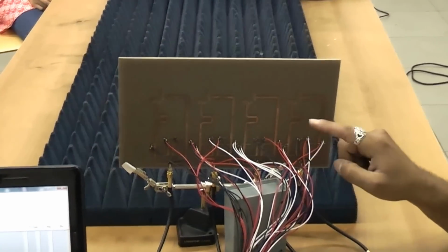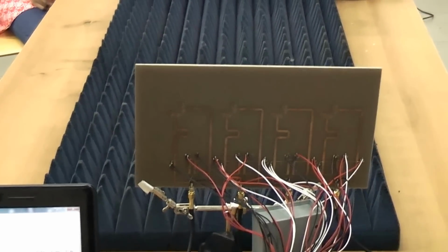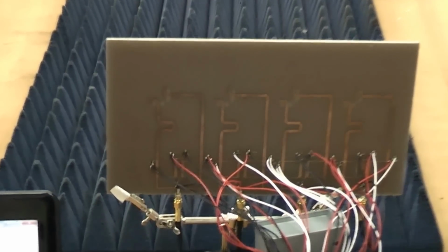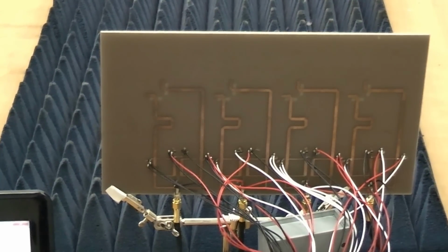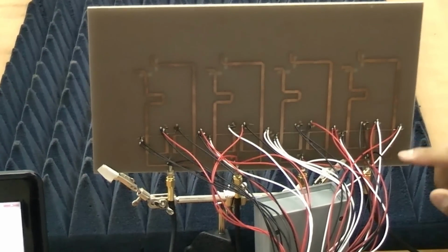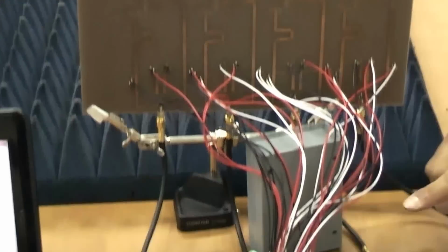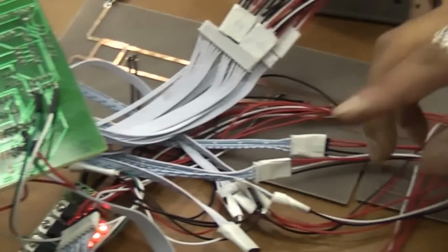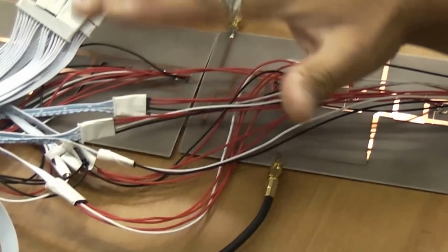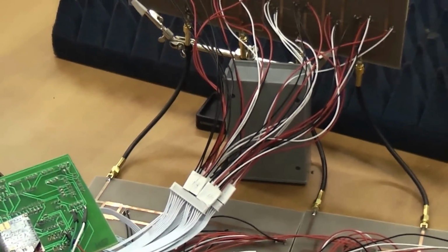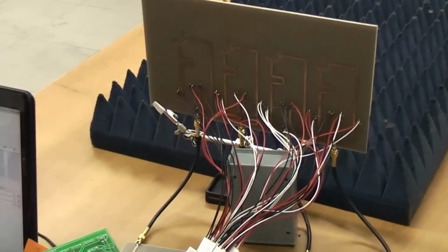The feeding lines can produce a polarization direction of X, or a polarization direction of Y, or a left-hand circular polarization. We're using the same couplers here, the RF switched couplers. Those couplers are fed through the PIC. All the software is reconfigured and programmed through our microcontroller, so we can have every different polarization and different combination of our system.